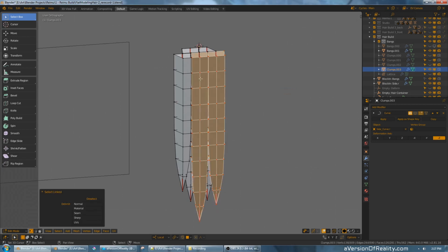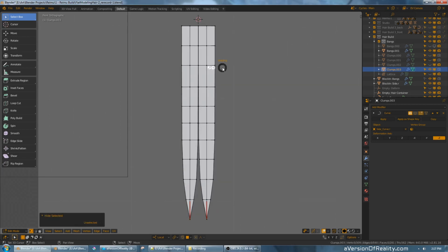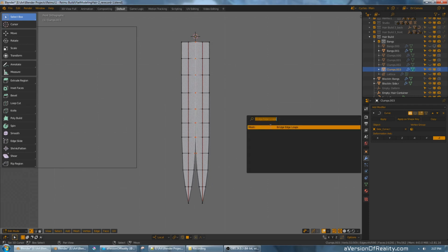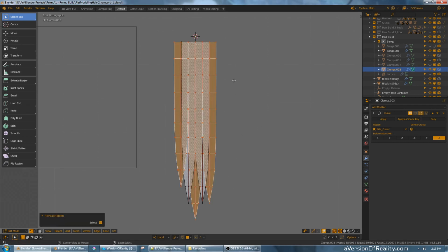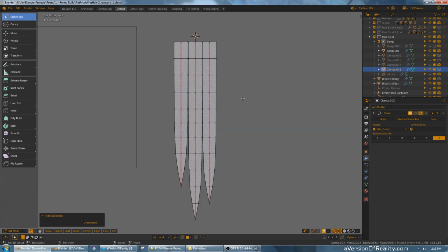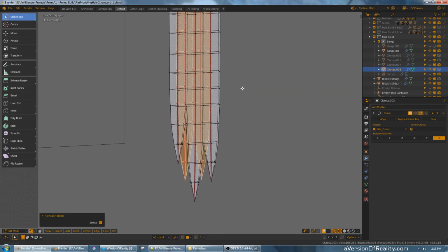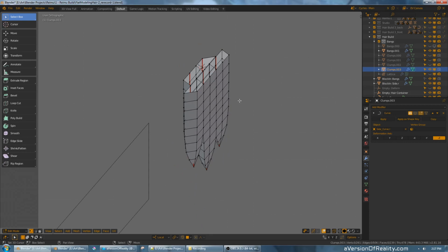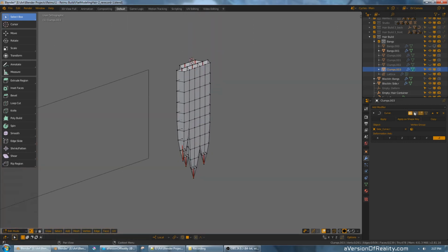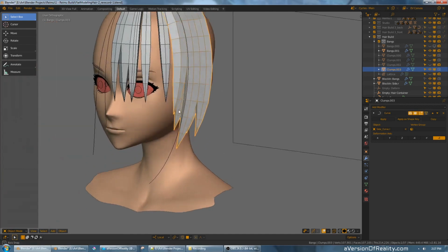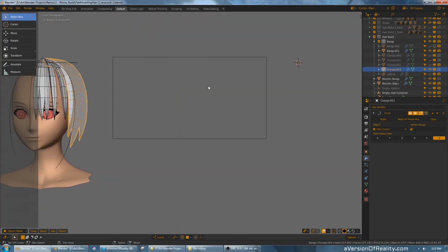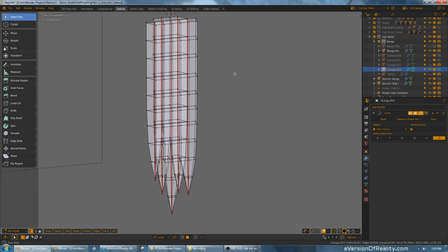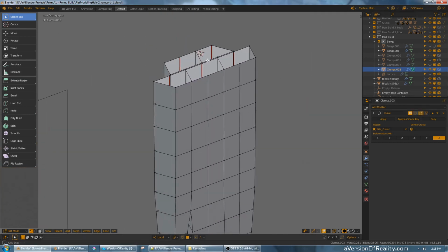That's the same process as we did in the bangs. I'll hide the ones in front to make it a bit easier. Grab these, fire Bridge, make sure it's on merge, and do the same in the front. Make these slightly different heights just to keep it interesting. And if we want, we can even join these two layers together. It's probably not necessary because when it's on the curve, the top layer is covering the bottom just fine. But I'll show you how to do it in case you have a more complicated shape that needs it.